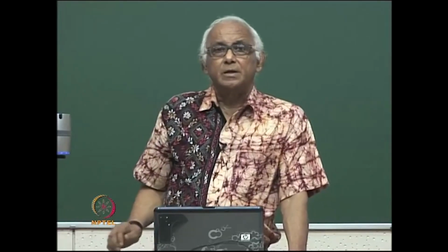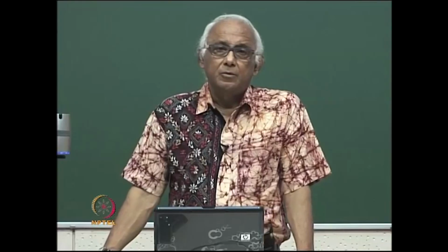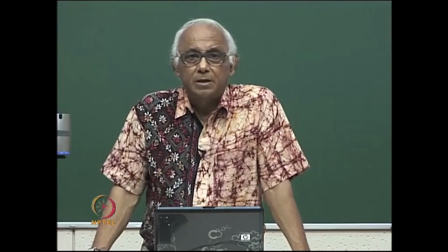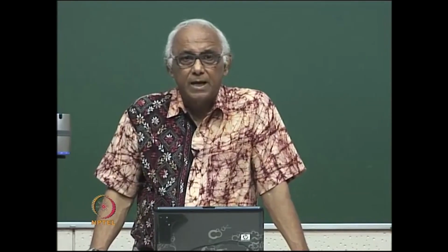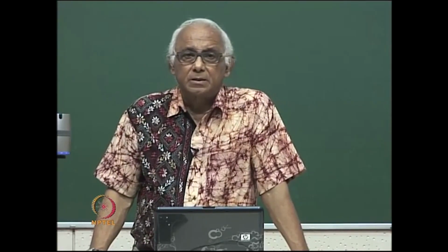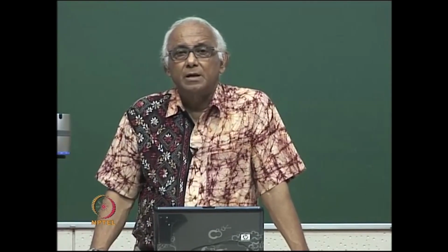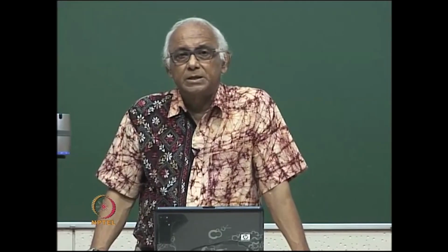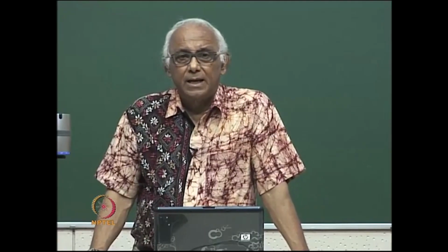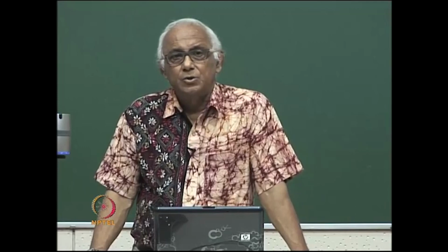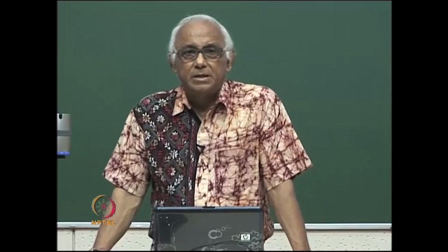So, let me summarize now what we have discussed today. We started with the earthquake measurement parameters. There are many earthquake measurement parameters. Out of that, we mainly discussed the magnitude of earthquake and the intensity of earthquake. Intensity of earthquake is a subjective measure and is generally measured on a 12 scale, whereas magnitude of earthquake is a measured quantity.